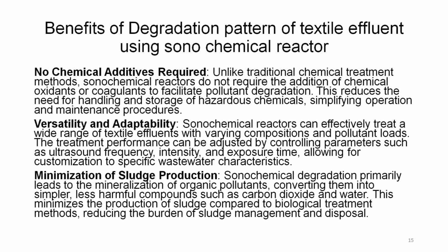Versatility and adaptability. Sonochemical reactors can effectively treat a wide range of textile effluent with varying composition and pollutant loads. The treatment performance can be adjusted by controlling parameters such as ultrasound frequency, intensity and exposure time, allowing for customization of specific wastewater characteristics.